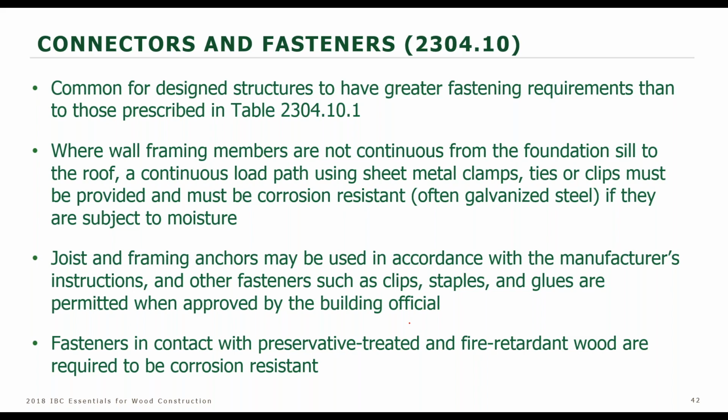In some cases, you know the performance. For instance, if there's a connection that doesn't serve lateral loads, but only gravity loads, and the range of floor loads and so forth, you use this table. But a reminder that all connections do need to be designed per the NDS. So the IBC doesn't contain all the provisions you may need. You do have a requirement in there for making sure there's a continuous load path as a design principle to take all the loads, the lateral loads especially, from the upper structure down to the foundation.